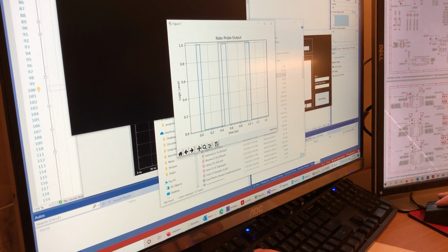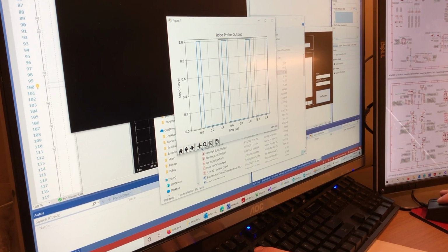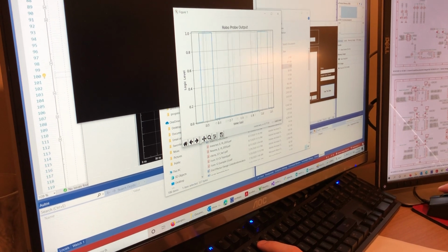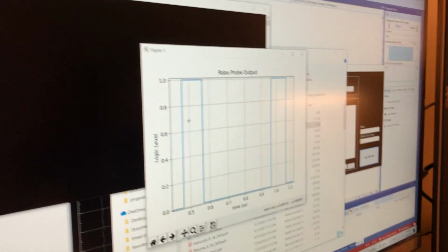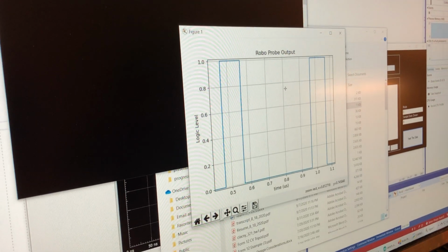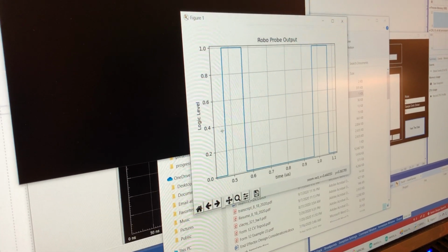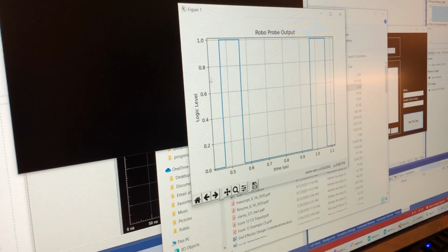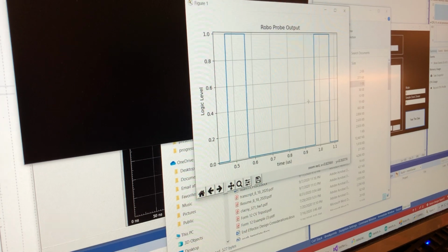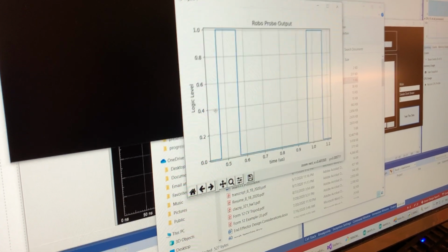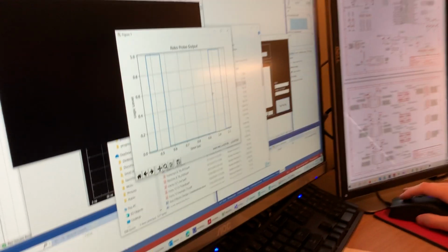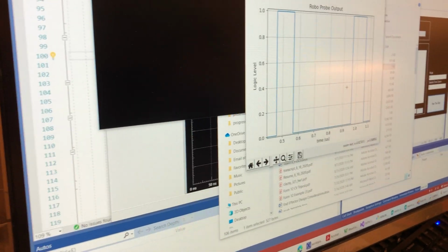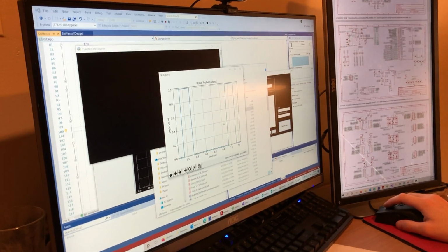And as I mentioned, when you run a 2 megahertz signal at a 30% duty cycle, you in effect have something that's a bit greater than 2 megahertz. So as you can see, the timings are not exactly precise, but we have correctly sampled the waveform, at least in terms of the digital values of the signals. And you can see that we have a signal with a half microsecond period, with around a 30% duty cycle, which is what this intends to convey.